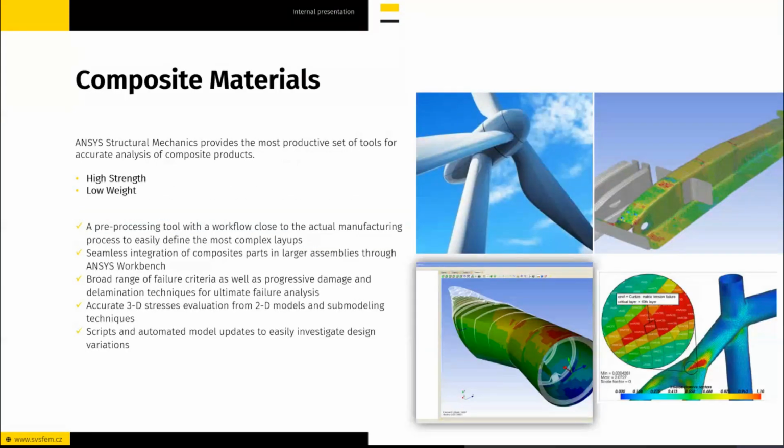And the question can be more complicated when you try to describe precisely the inner structure of the blades. There is a sophisticated, non-linear structured composite which provides high strength, low weight, but which generates also hotspots, local effects, fast phase changes, delamination, and new types of instabilities, and so on.